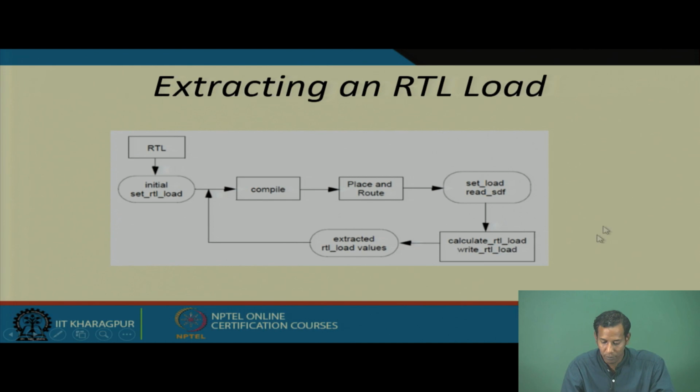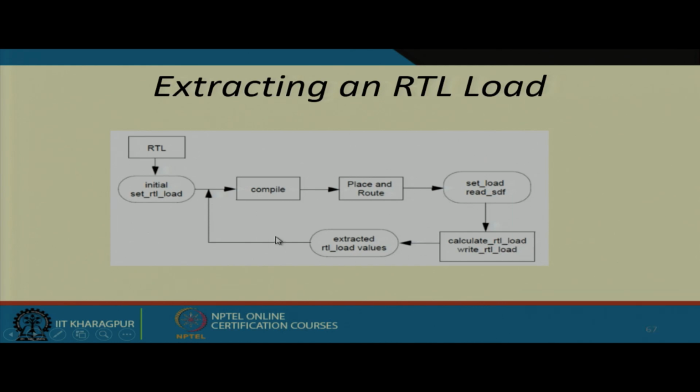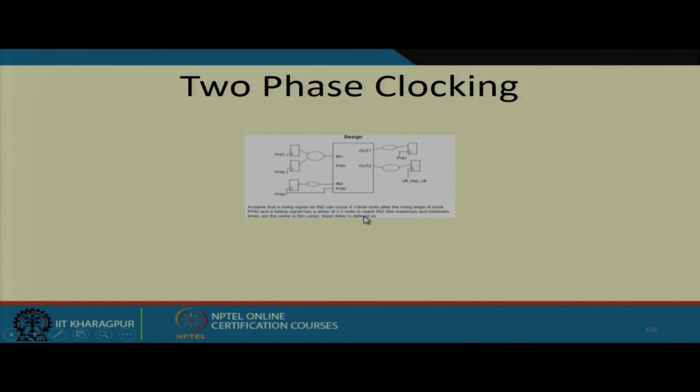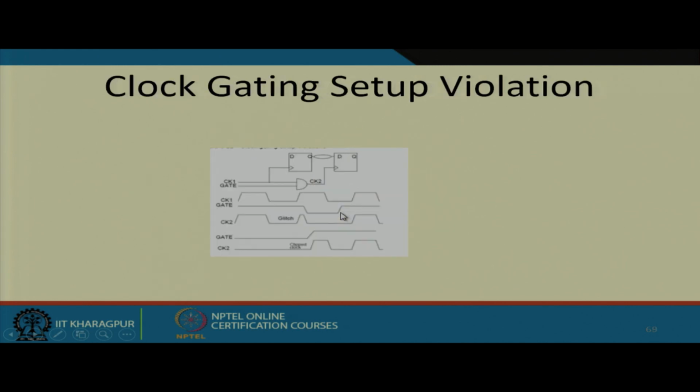Now, the actual time will be calculated based on this particular loop. If the actual time is more than 5, at that time you will get negative slack. If this path corresponds to a lesser value than the required time, you will get positive slack.